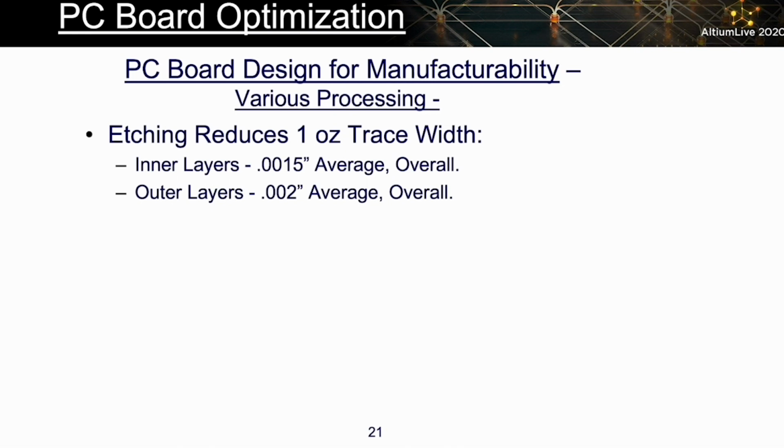That's a special order. They're not going to be using standard materials, which means they can't build what you've asked without a special build, and you will pay extra for it. The point is, don't put 2 mil lines and spaces or even 3 mil lines and spaces on the outer layers of 2, 4, and 6 layer boards when they're using standard copper weights, because they can't produce it effectively. Know what can be done. Talk to the fabricator. Drink in their knowledge. Ask them the questions. What can you do and what can't you do? Can I do this? Can I do that? We're going to talk more about that in a minute.